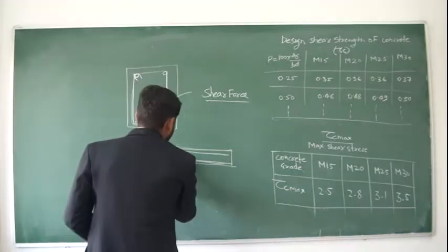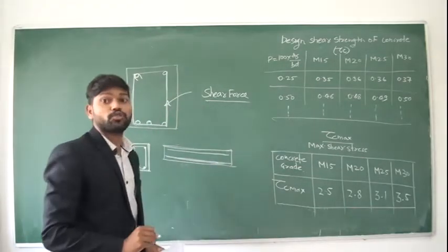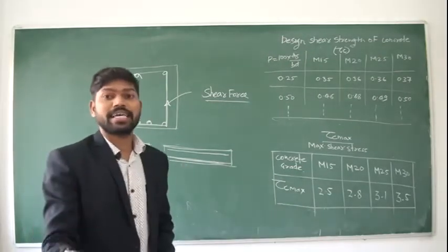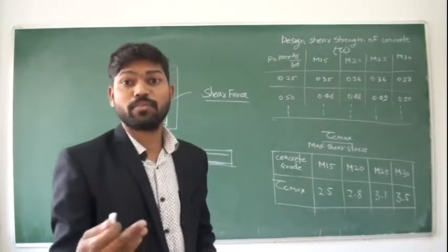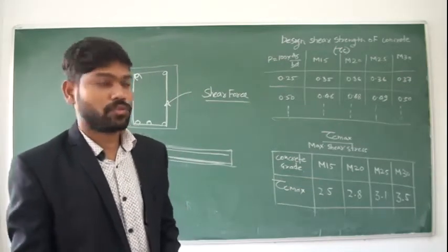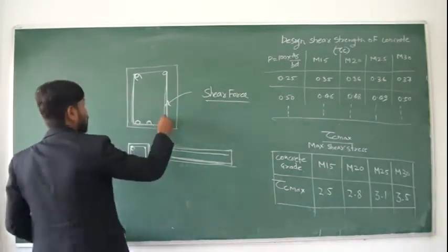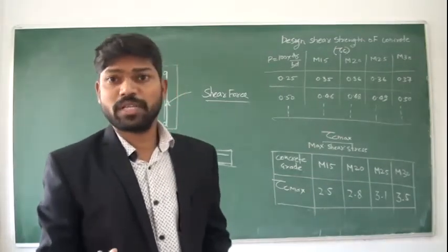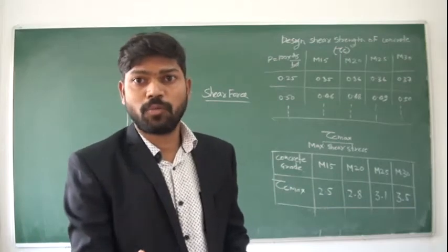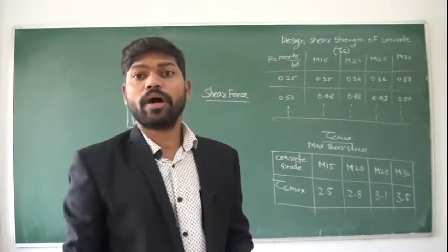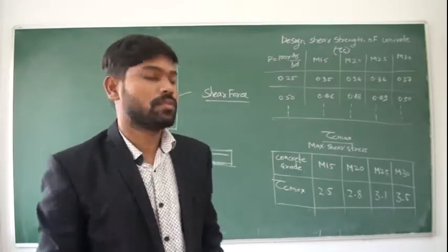And this is called longitudinal reinforcement, you can say tensile reinforcement, reinforcement provided to resist tensile force. But this vertical stirrup is called shear reinforcement. Now, is shear reinforcement provided only in the vertical stirrup form? No. Shear reinforcement is provided in 3 different forms.